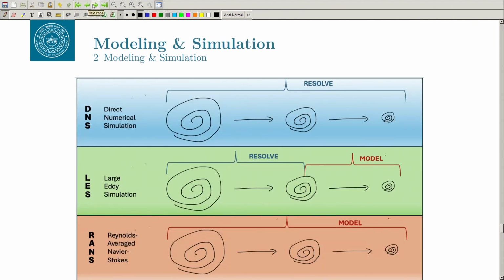Now there are many approaches to solve this problem. Coming back to the big question that we initially asked when we started this discussion on turbulent flow, why is it difficult to simulate a turbulent flow, right. If you want to simulate a turbulent flow, there are 3 approaches mainly, DNS, LES and RANS. Of course, there are intermediate approaches, like a partial DNS, partial LES, partial RANS, called detached eddy simulation, DES. But mainly 3 classical approaches.